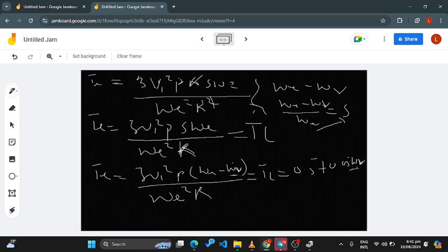Is that okay? So to make this understandable, there are a lot of ways you can go about it. One way is that I'm going to do the conversion straight away. Electrical speed is equal to pole pair times mechanical speed, let me call it omega m. So when people see omega r here and omega r here, they say, oh, it's the same thing, so the answer we got is the mechanical speed. No, it isn't. You got it?